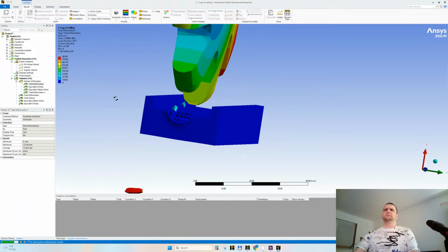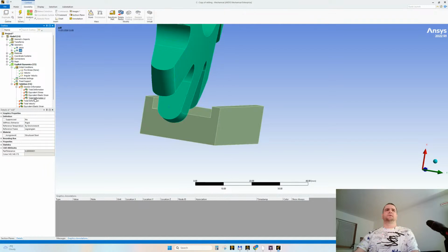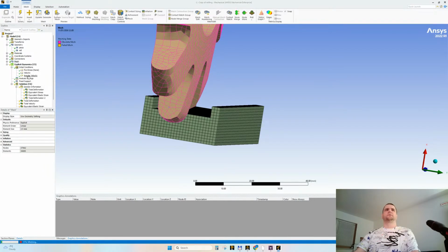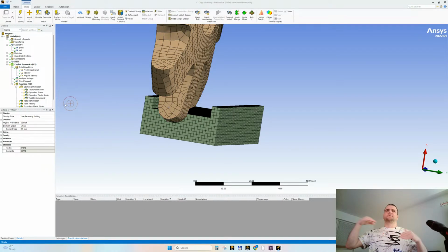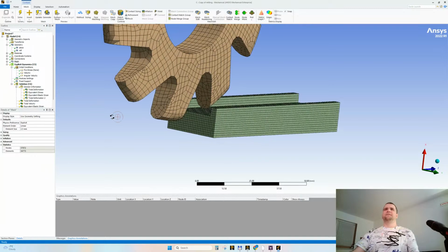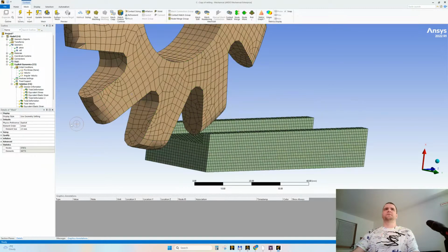Okay. Let's change the stiffness again, back to flexible, because this approach gives problems. Due to the increased stiffness, it bounces back. The infinite stiffness of this being rigid, it bounces back. Also, this is pretty stiff due to the mesh density, which is very high. It's very fine.